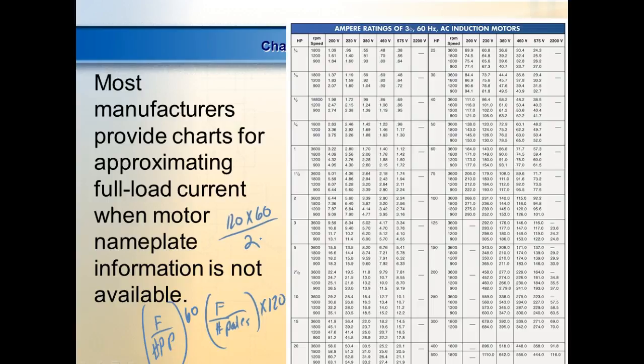So if I got a motor that I want to control the speed of, I can't change the poles. What do we change? Got to change frequency, but we can't just change the frequency because of something called volts per hertz. We'll look at that later. They call them variable frequency drives, but the name is changing. People understand that you just can't change the frequency. You got to change the voltage in the motor too. So I call them variable speed drives, but everybody over in Germany will call them what?